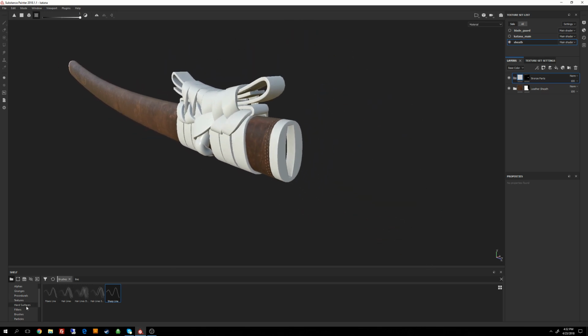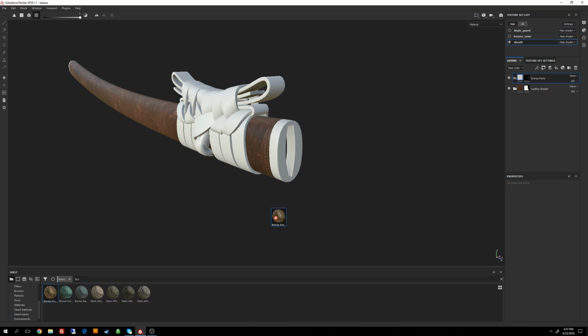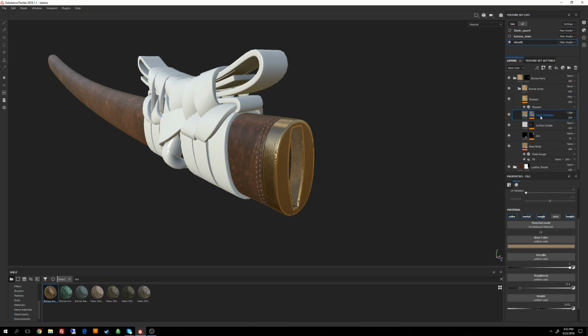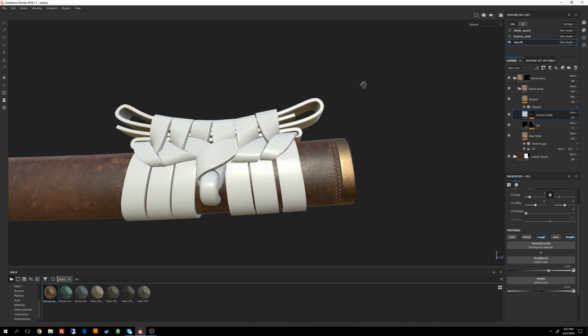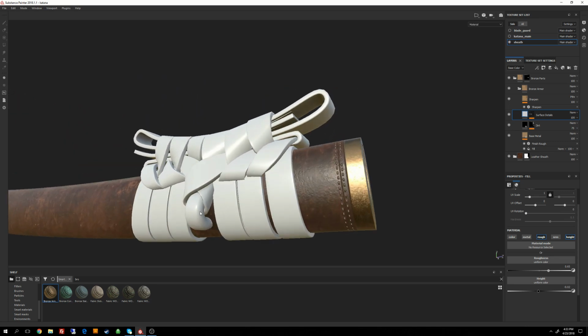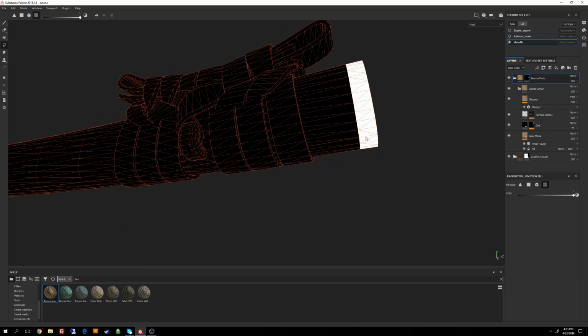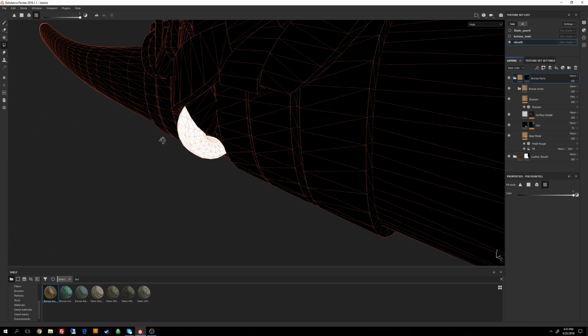And let's go ahead and search for our bronze material. It should be under Smart Materials. Drop that right on top of our bronze parts. Okay, and we're going to want to adjust this. You can see there's that issue again with the edge wears. So we'll just go to this edge damage layer and delete that. That clears that up for us. Actually, before we proceed with that, we need to also get this piece right here. So I'm going to go back into our bronze parts material, and select this piece in here. Make sure we get this in here as well. There we go.